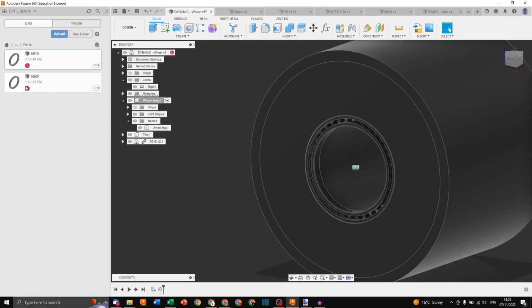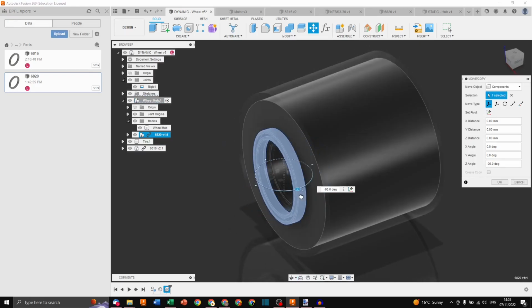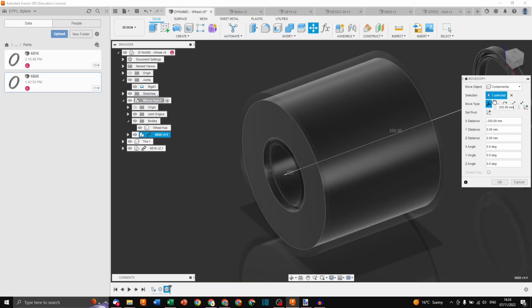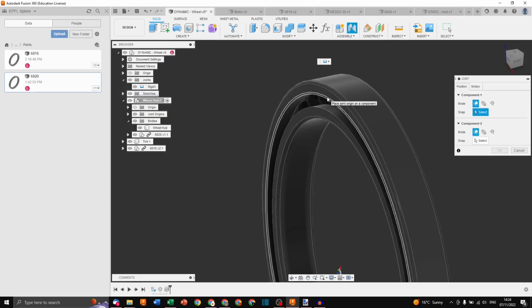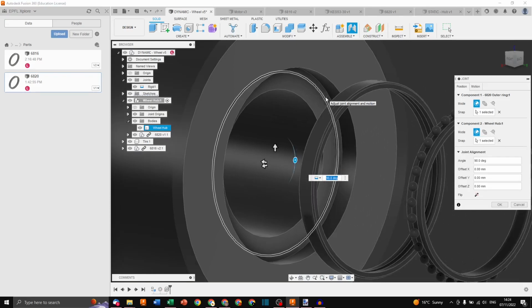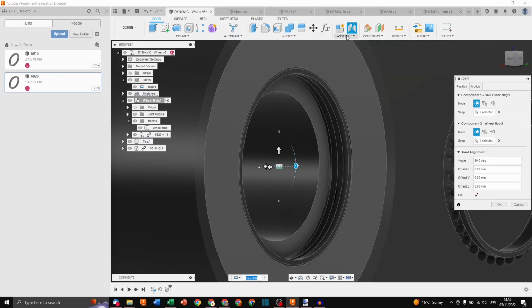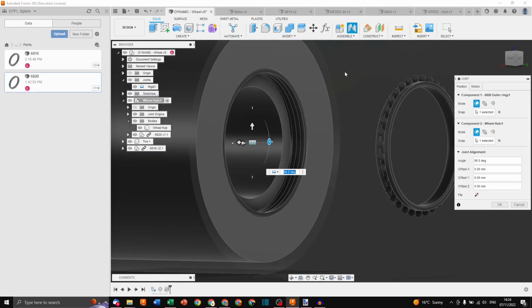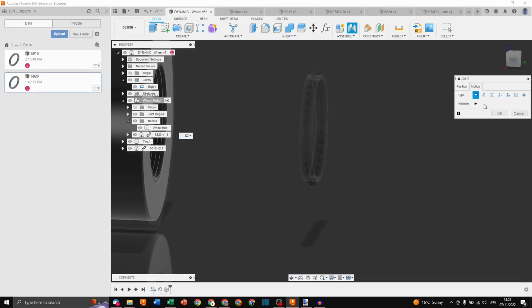So front bearing, good. Rear bearing, right click, insert into design. Perfect. This time I won't add joint origins. You can see it's bigger, great. Spin it exactly 90 degrees. Translate it. Okay, great. Get into it. Joint between this circle and this inner race of my wheel. Perfect. Outer race, I can see it's clean, how I want it, great. So I didn't add a joint origin. I just clicked on the right parts of my design and it automatically added the joint origins and clipped it in. So we're good. Motion rigid, perfect.